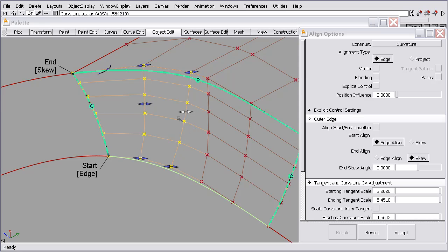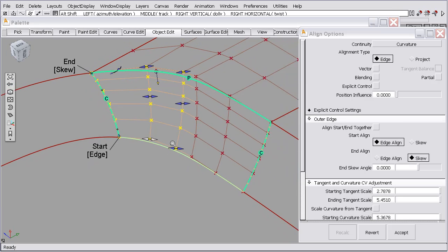But what I would like to do is smooth this structure out a little bit and get rid of this taper between these two. So I'm going to adjust this slider, and that tapers that modification from one end to the other. Then I could grab the tangent row and slide it, and while I'm sliding the tangent row, you can see that the curvature row also moves. That's because it's continually updating. We have our performance options set to during transform. So I'm going to place that row in a spot where I like it, and I think that looks pretty good.